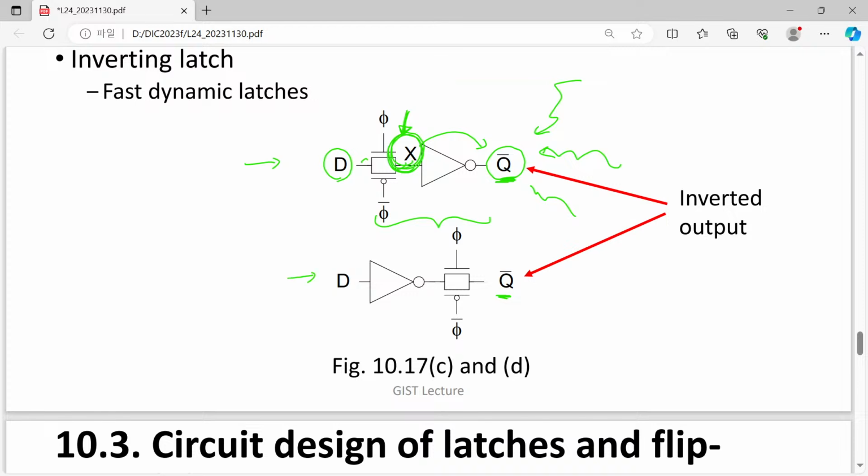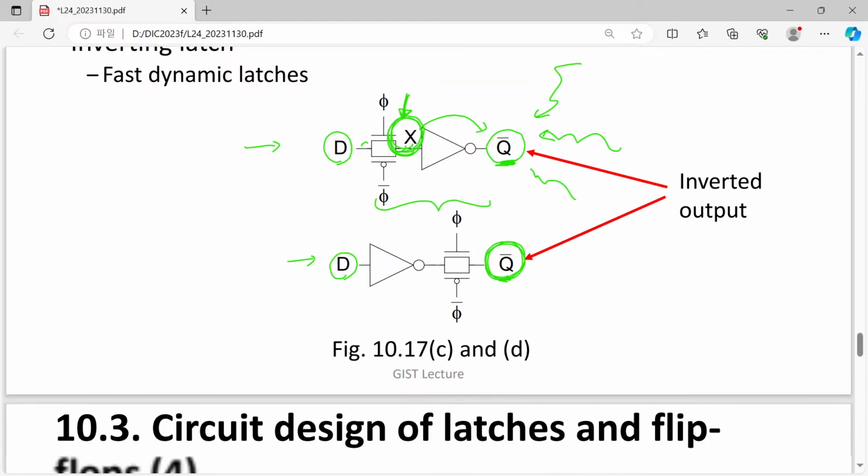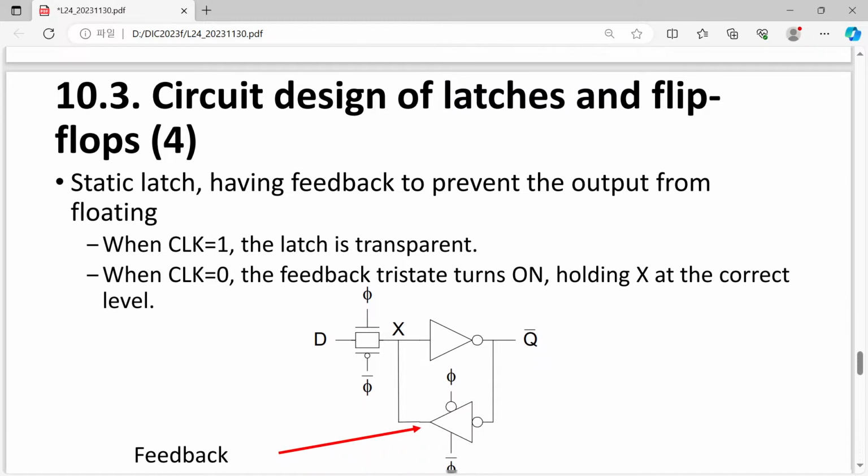In this other case, okay, now we can avoid the diffusion input problem, but the output value, our state variable, is not protected. Then obviously maybe we can add inverters both in front of and after the transmission gate. Okay, we will see later.